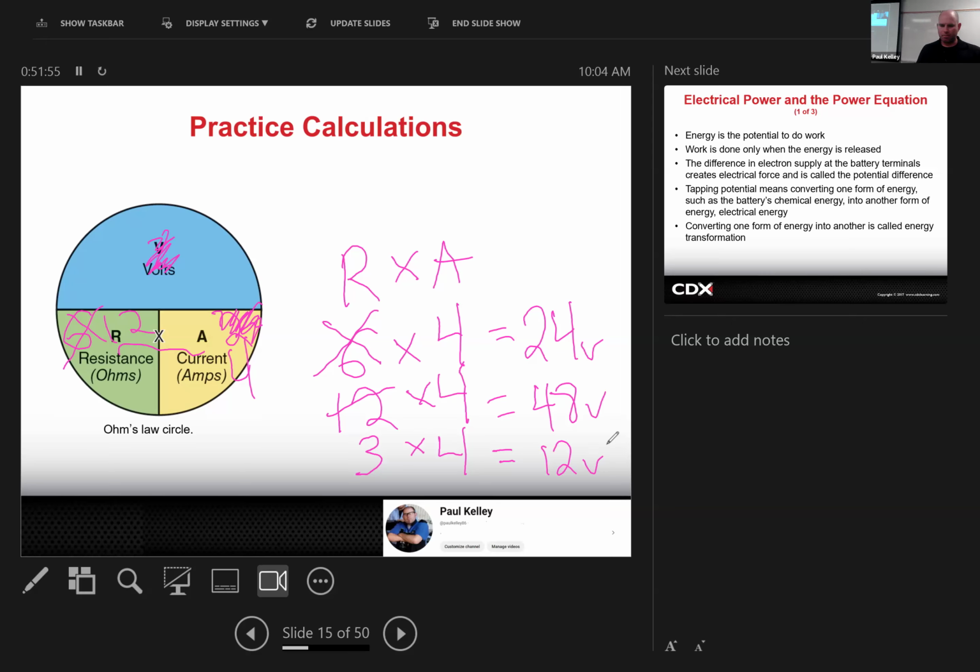One of the reasons we run into probably so many resistance problems in automotive, as you can see, we're running a 12 volt system. So if we have a 12 volt system, the amount of resistance has a really big effect on amperage, because we only have 12 volts, right? Imagine if you know these homes and buildings are running 120 volts or so. Imagine if we were running 120 volts in the vehicle. If there was a little tiny bit of corrosion on the connector, it wouldn't make that light bulb go dim. You'd have to actually have pretty substantial corrosion.